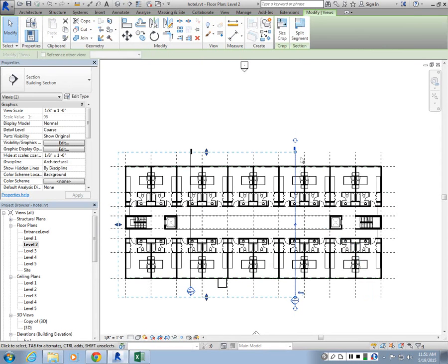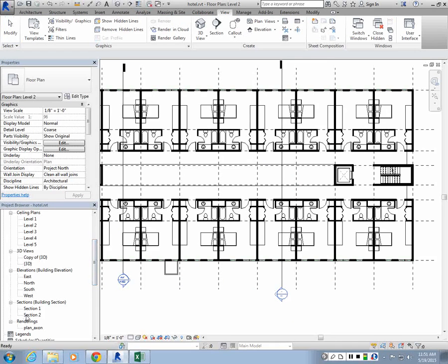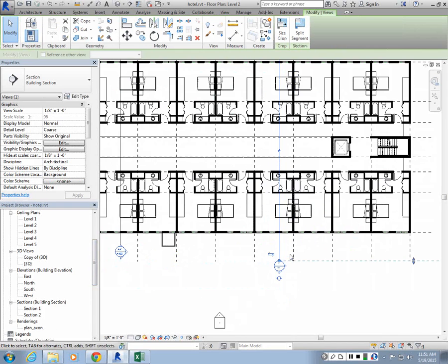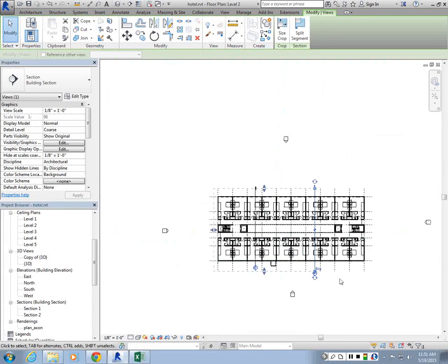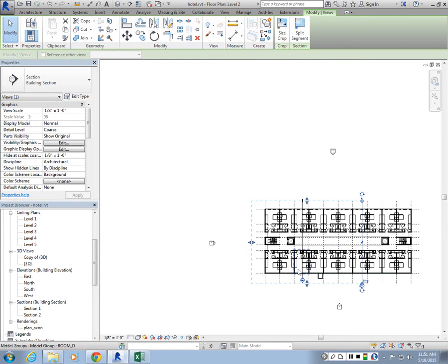You can place a section. Once you place it, it's already created under the project browser. I have section 2. You can change the direction of it using these arrows, so you can look to left or right. You could also control the depth of your look, right? This is similar to the view range I was talking about in plan views. You may want to see the buildings behind your drawing or other types of features. Maybe the building is at an angle, so there's a portion of it here, and you may want to see it or include it in the drawing as well.